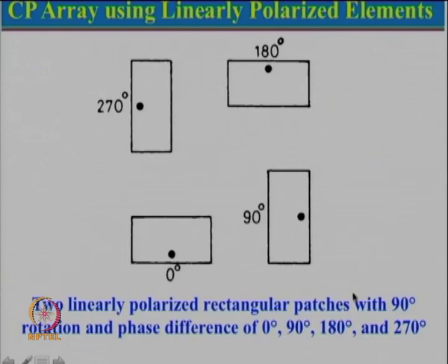Now, from a far away point, if you look at these two antennas, what do we see? A far away point is far away, and these are the two patches here. It actually sees almost the same distance, because this distance is very, very small. So, really speaking, at a far away point the amplitude received from these two will be the same, and since these two are fed at one angle 0 and one angle 90 degree, these will give rise to circular polarization.